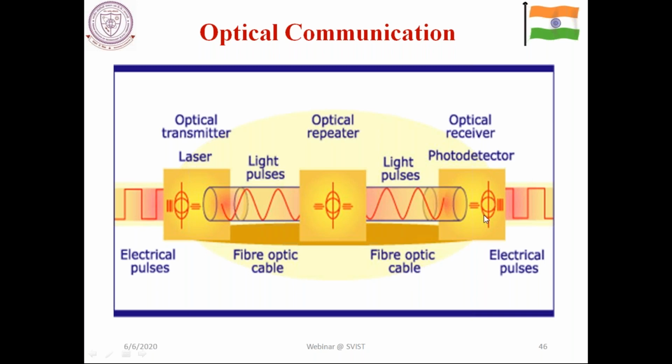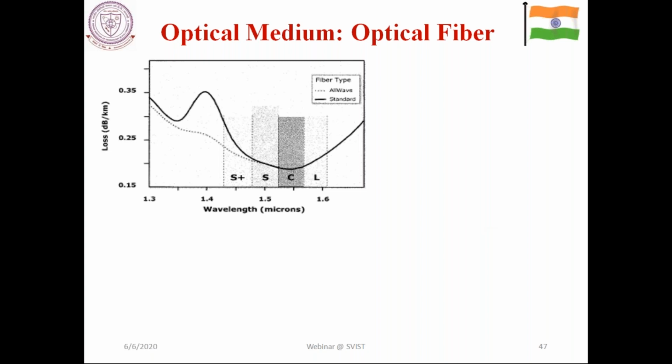Okay. So here I can show you the optical fiber. Once you see this particular one, in this case you have a certain attenuation. If you see the characteristic graph at 1550 nanometer, or 1.55 micron, you can observe the minimum attenuation, and how much is it? 0.2 dB per kilometer. It is specified. Okay. Now what is happening?